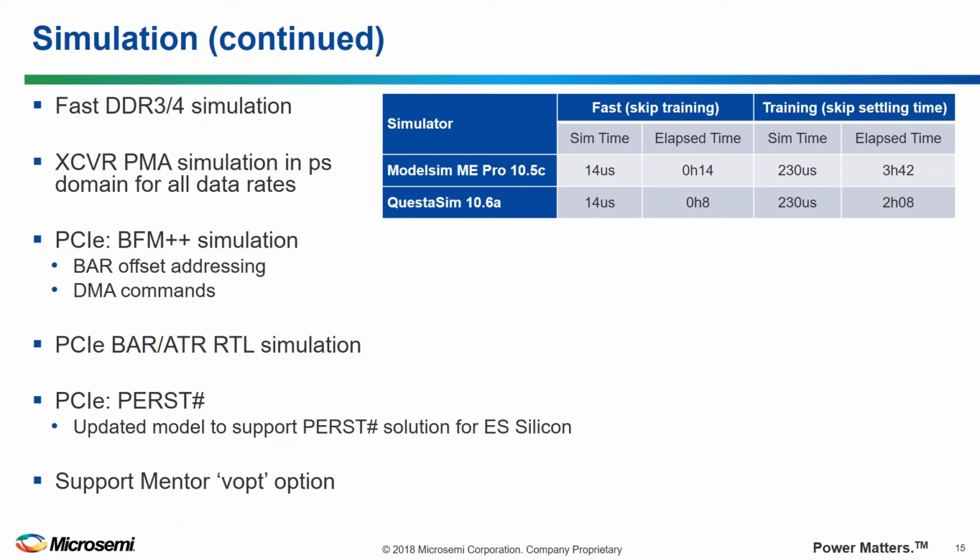And it allows you to verify your design at multiple stages. The design entry stage, where you're doing RTL simulation, gate level after synthesis, and timing simulation after layout, where you could take the netlist as well as the SDF file that's exported from the layout tool and do a timing verification to make sure you're meeting your timing objectives.